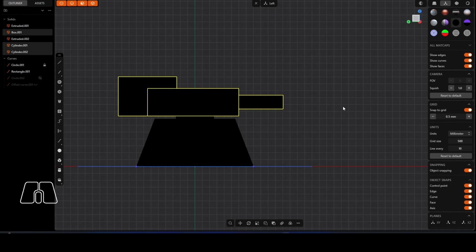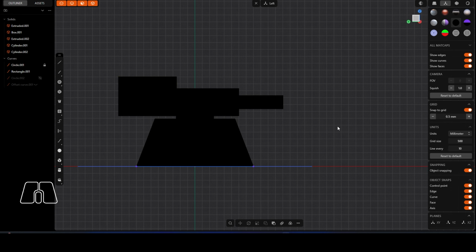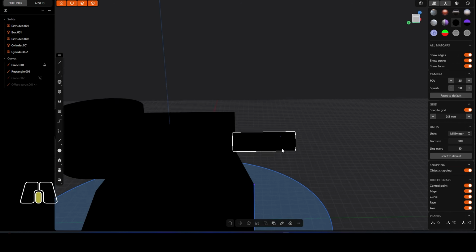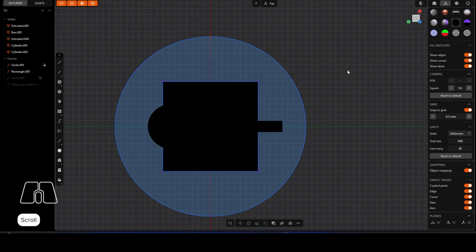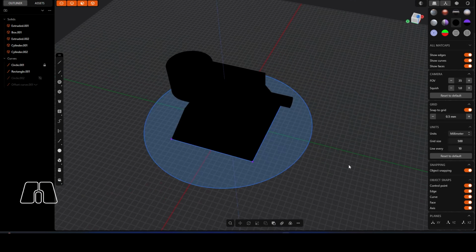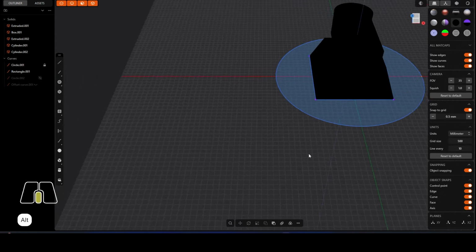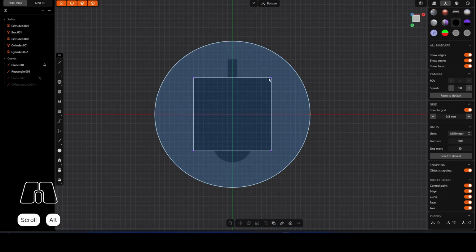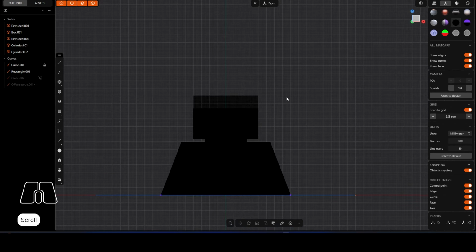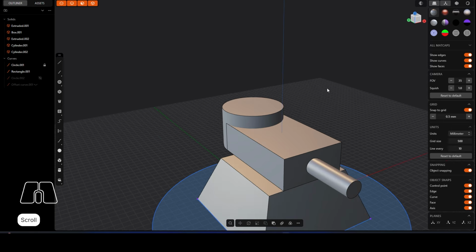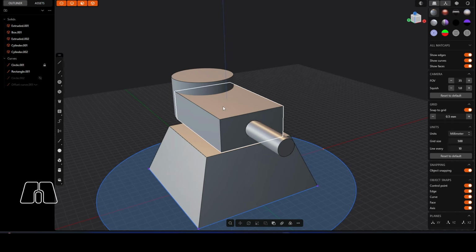You can use your different shading modes as well. So again, if you want to see silhouettes, which are super important for your design process, I would advise just use the shaded mode here, and it's really good because we can jump in and you can see now the shapes that you're creating, and this is going to be the silhouette. And again, you can look at it in perspective. We can change it to the front. So if we look at the front view, you can see we've got a basic silhouette at the front, so perhaps we need to add some features to the side now. So it's really handy in terms of the block out process.